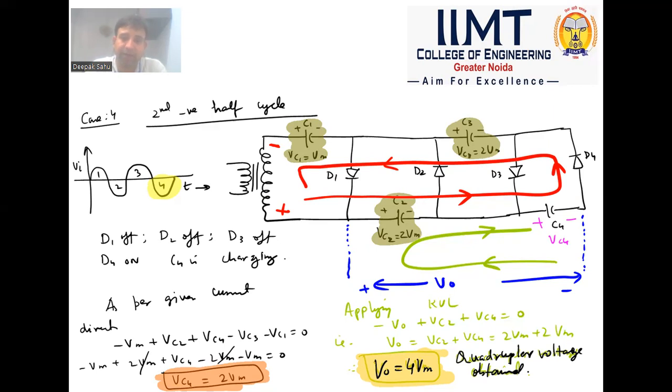Now, this is a lot different from rectifier circuits, because rectifier circuits are generally based on filtration and such. In these circuits, no filtration is used, and basically only diodes and capacitors are used. So this system is lightweight and easy to use. There is no extra requirement of heat sinks and things like that, which are needed in rectifier and voltage regulator IC systems. As I said earlier, a very large range cannot be handled using it, but a mid-range can be. So hopefully this session has cleared your doubts regarding voltage multiplier systems.